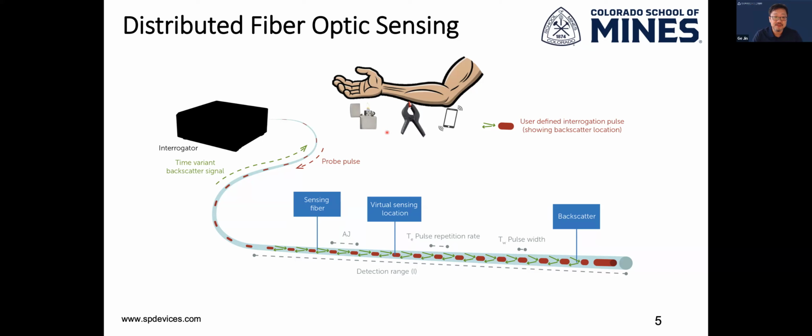The idea here is that we connect one of the fibers with a sensing measurement instrument called the interrogator. This interrogator sends laser pulses that travel down the fiber, and because there are built-in heterogeneities and defects in there, any part of the fiber will reflect, or backscatter, a little bit of the laser energy injected into the fiber backwards to the interrogator.